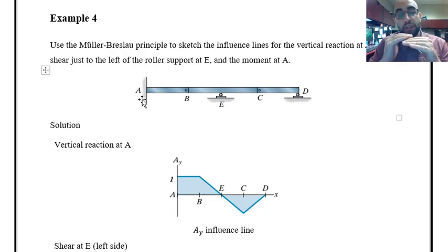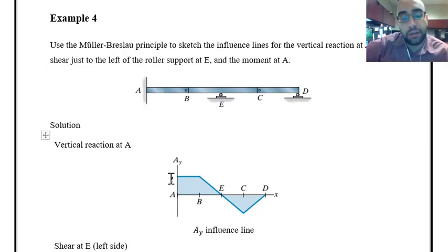So just a unit displacement, and it is completely horizontal because it cannot have any rotation. You can see that over here. We have a hinge over here, so it can rotate from point B to point C, another hinge at point C, so it can have the rotation like this.